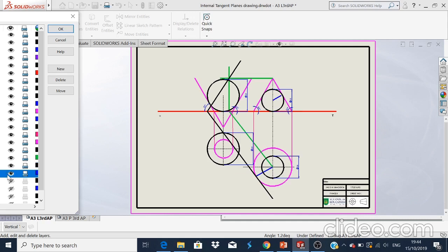So the next step is we have to find the points of contact where the trace meets the spheres. What we do is we draw, here's our normal to the cone. So we draw our normal at 90 degrees to the cone, and that's represented there in our elevation. And where this line crosses the cone here, that's brought down to our center line in our plan, and we rotate around this circle.